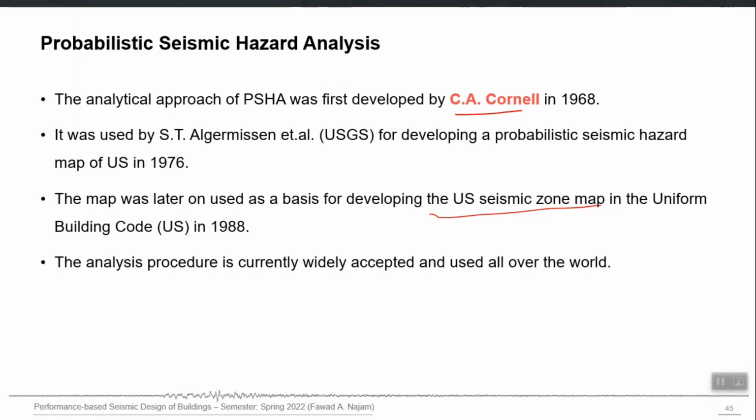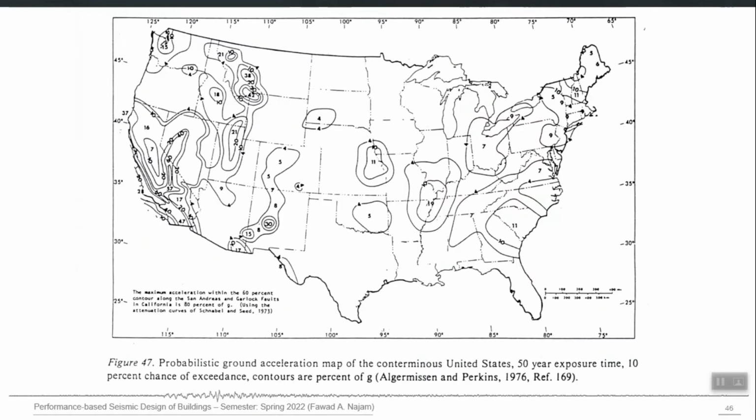The idea was that we perform the PSHA for PGA, considering PGA as our hazard parameter, and then make different zones which have the same or similar range of PGA. So nowadays this method is widely used. Several new approaches have also been developed recently in this PSHA methodology, but we will be studying its very simple version. I will give you just an overview of the overall methodology. Details I will skip, and I have separate video lectures in which I go into a little bit